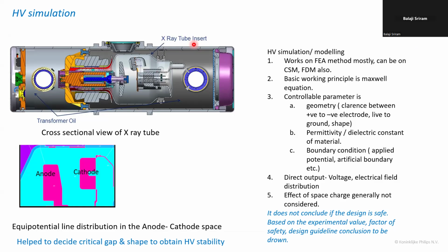If there is more branching, more secondary electron creation, it tends to a failure. That's where the vacuum and all these things come in. So our experience says 11 millimeter to 16 millimeter with 10 power minus 6 torr pressure is just optimal. Okay. Also, do you use a rotating anode design or a static anode design?